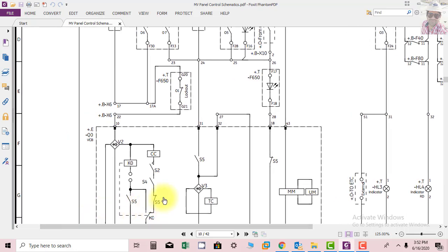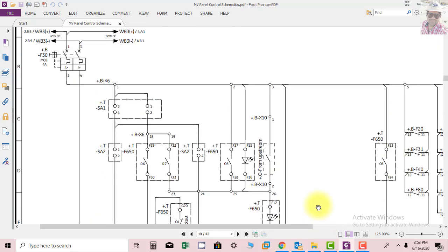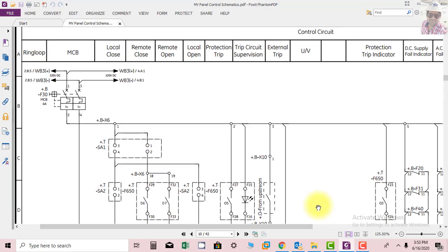This is a feature which is required, especially now as per the new IEC standard, because previously the 11 kV substation DC supply failed in many places and a fault came, and because there was no DC, the breaker did not open and it resulted in a big fire. So nowadays the new specifications recommend that as soon as the DC supply fails, the breaker should open. So this part deals specially with that section. So you can see it is under voltage trip.